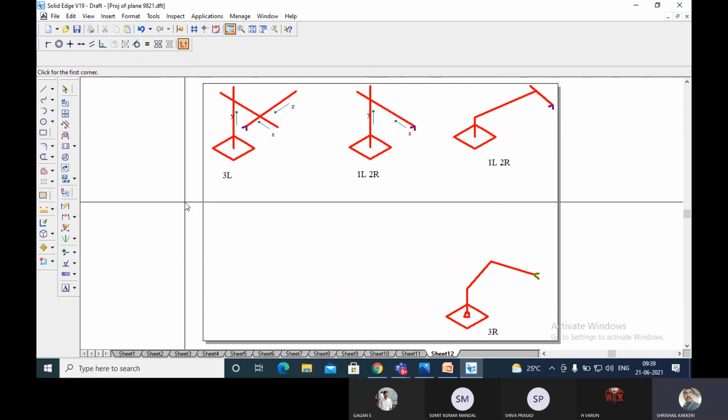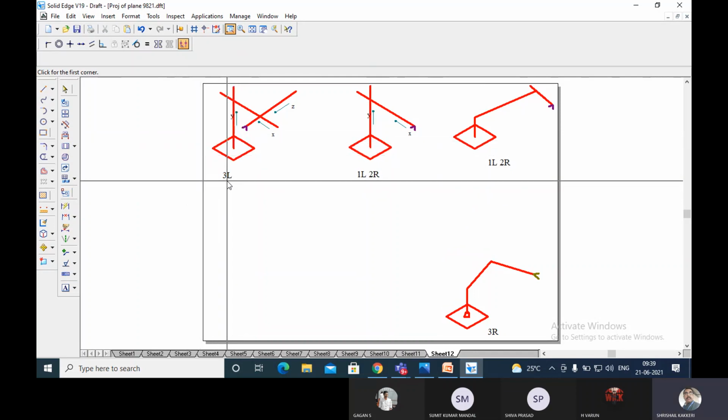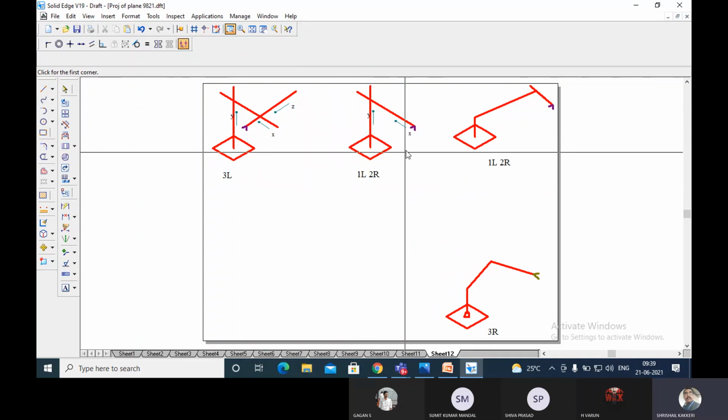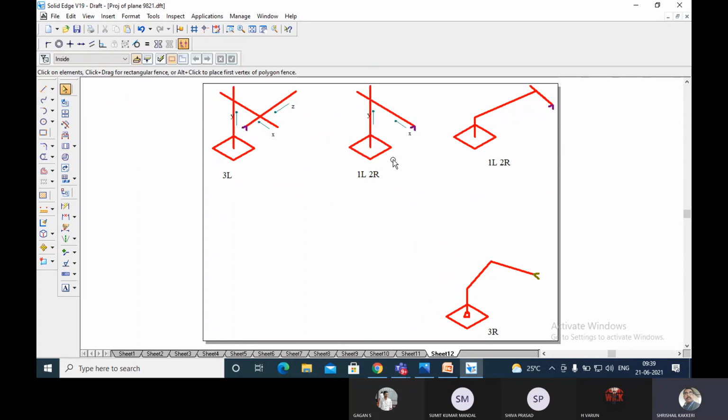And the mechanical stability will be very good in this, and it can perform pick and place. And mechanical stability will be lesser compared to this one, because one rotation joint is increased in this. So to compensate for that, we'll be using a better controller, and this can perform pick and place. This also can do pick and place along with simple welding and spraying operations.